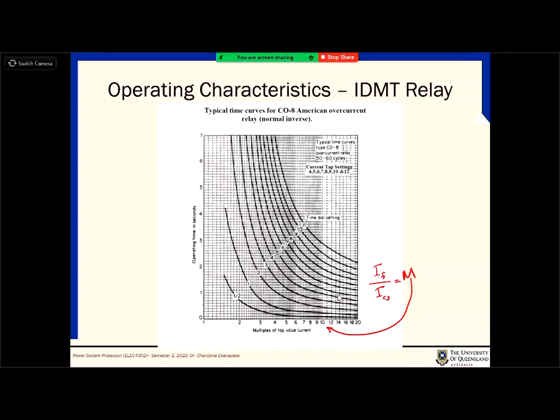But when it comes to numerical relays, because mechanical relays usually follow these sort of settings, it's really hard to come to a certain value in between, because it has sort of fixed or defined characteristics for each level. When it comes to a numerical relay, you can define these things using an equation. It's quite easy.